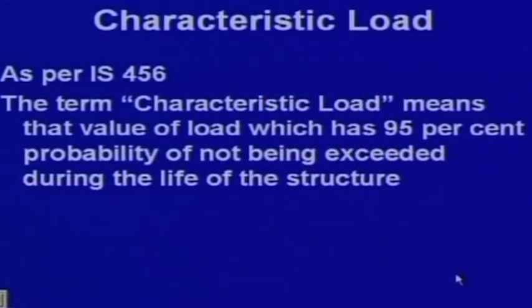According to IS 456, the characteristic load means that value of load which has 95% probability of not being exceeded during the life of the structure. So, even then we are considering one limiting value, and we are assuming that in a few cases it may go up and cross that particular limit, which is also possible.